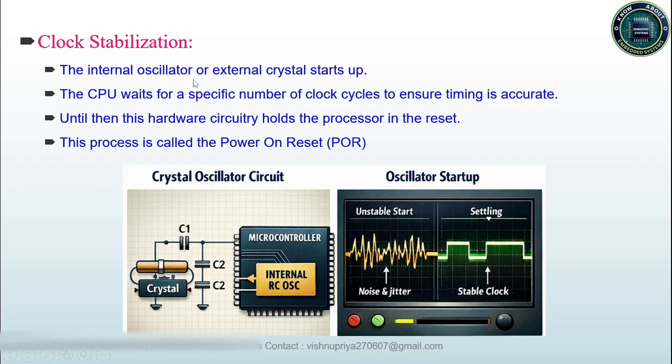The internal circuit, either an internal RC oscillator or an external crystal oscillator, will wait, that is, the processor will wait with a specific number of clocks to ensure the timing is accurate. That means timing also should be accurate and stable. So until then the hardware circuitry will hold in a power on reset state only.